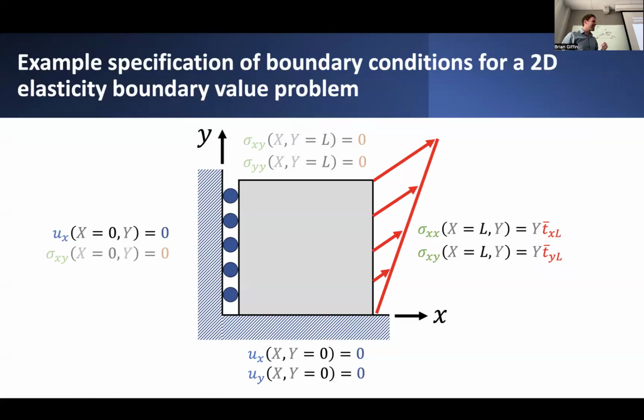And the reason has to do with the fact that if you can only push on the surface or impose some kind of shear force on the surface, there's no way that you can directly control the longitudinal stress that's going to develop along the surface. The membrane stresses are going to be what they are. There's no way that you can directly control those by applied loads. So really, it's only the components of stress exposed on these surfaces that you can have any control over.